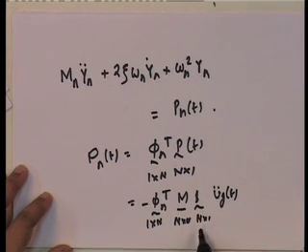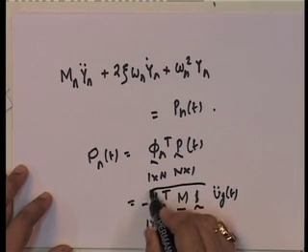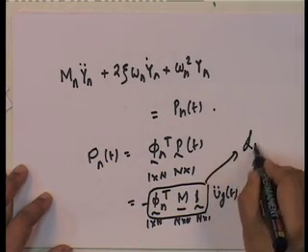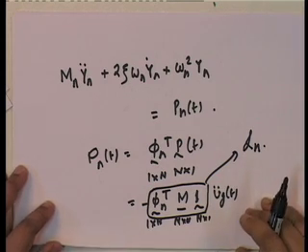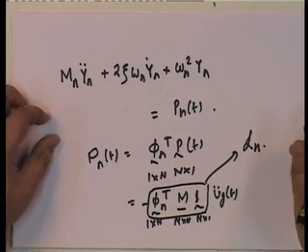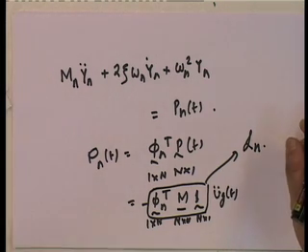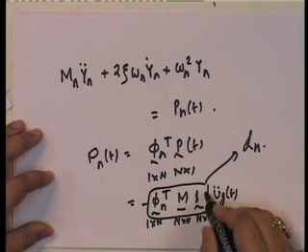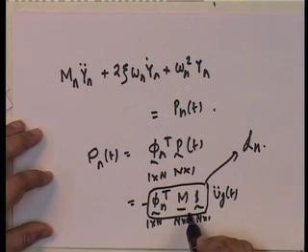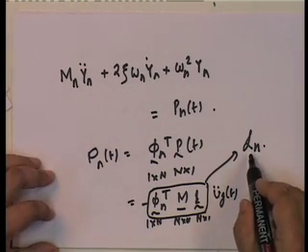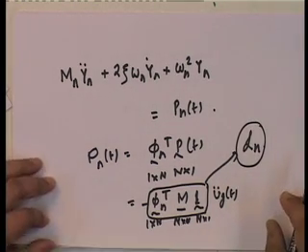So, we do get a scalar, and this term we call Ln. Remember yesterday when I solved that specific problem, I had defined that the base shear was given by Ln. Okay. So, this same phi n transpose m into 1 is Ln. This is the same Ln that we defined yesterday.